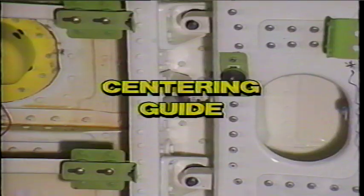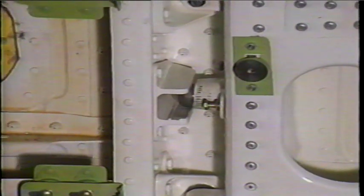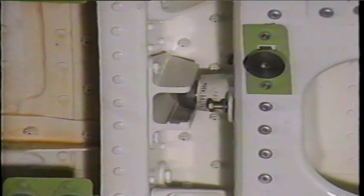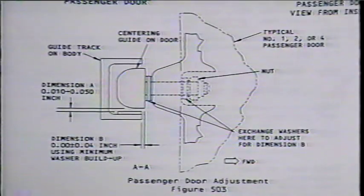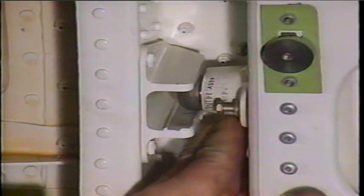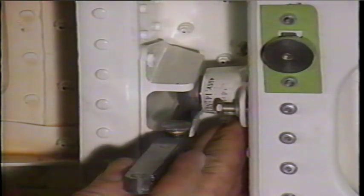The next adjustment is the door centering guide. The objective is for the centering guide to smoothly and freely enter the guide track on the body as the door is closed. Check dimensions A and B to see if adjustment is needed. Adjust gap A between the centering guide and the guide track rub strip by moving the centering guide fitting up or down on the serrated plate as needed.